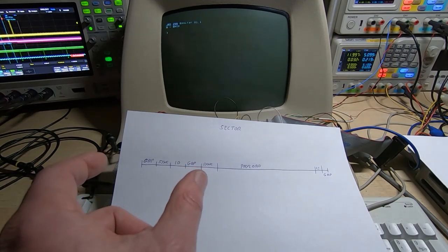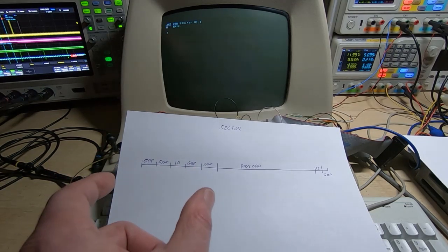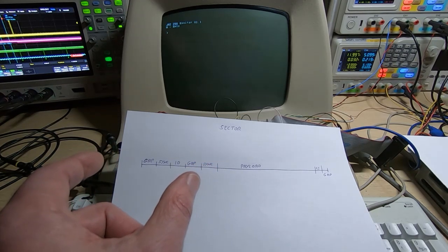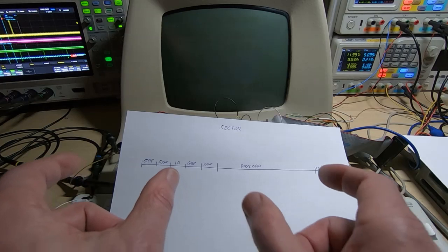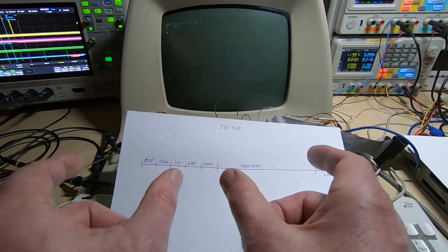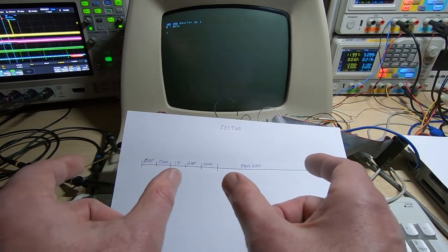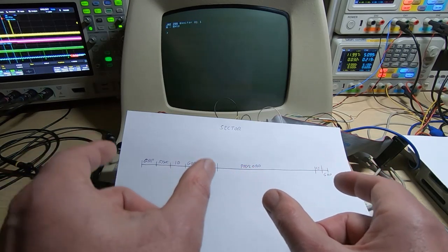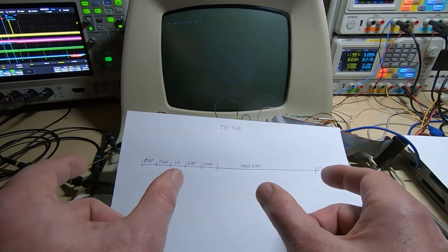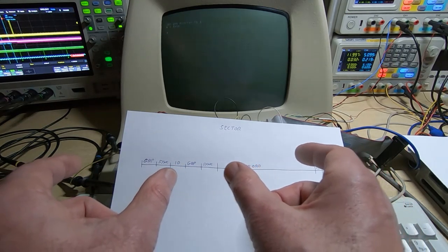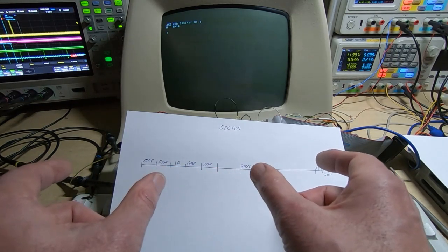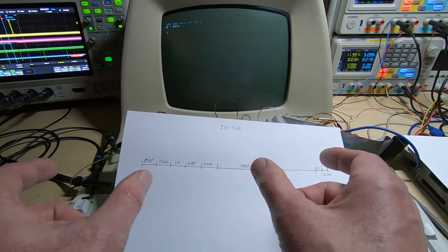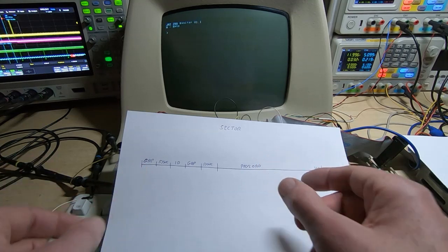So if we take a sector and we're going to try and read it, you might find there are variations in the rotational speed of your disk drive. So rather than 2 sectors being butted up against each other, they're separated with some gaps. That allows the system to read one sector, and if it's getting slightly ahead of itself, it can skip or add to the number of bytes in the gap, so it allows the system to adjust the overall speed of reading data from the disks.